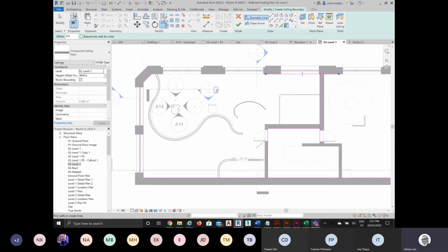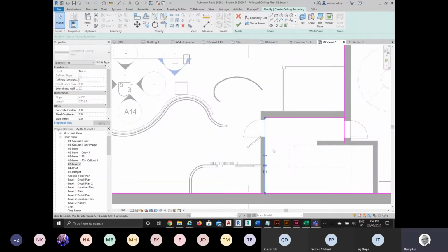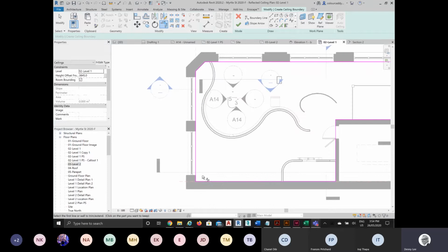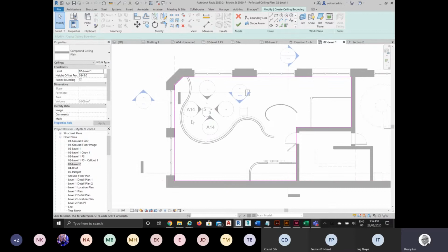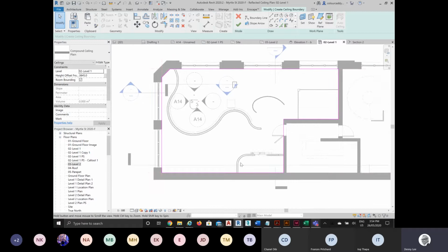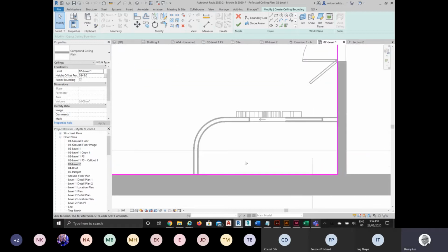So if you just have one ceiling for an entire apartment, that's probably okay. These lines here just need to be flipped. So you should think about putting your ceilings just on the inside face of your walls. So think of it as a drop ceiling, one that drops down essentially inside your walls. Some of the walls may sit under the ceiling. So this curved wall here could sit underneath the ceiling. And that'd probably make sense because you probably don't want to have a ceiling that needs to be framed and built around that curve.